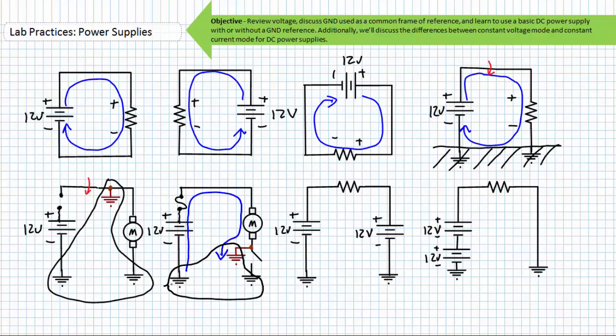But for right now, you should understand that a high-side switching arrangement is using the fuse and the existence of a ground connection to make sure that the motor doesn't start unexpectedly. And in a low-side configuration, an accidental ground connection can accidentally start motors. It's for this reason high-side switching arrangements are preferred to low-side switching arrangements.